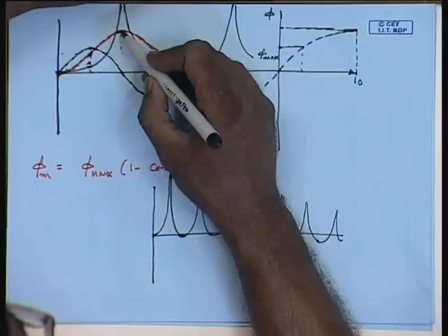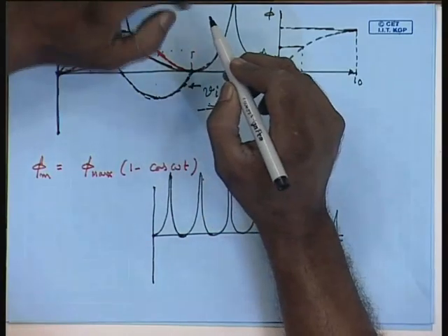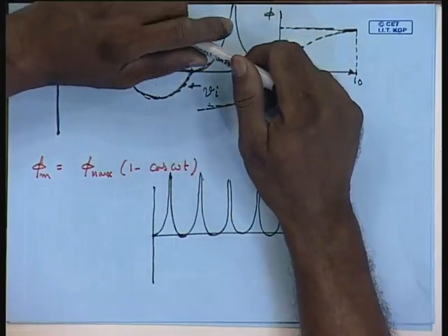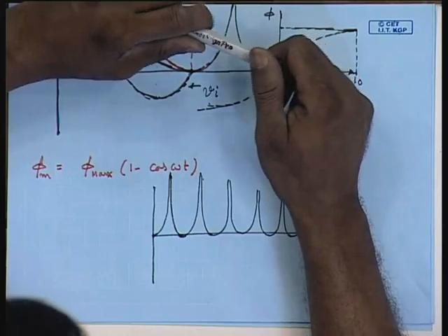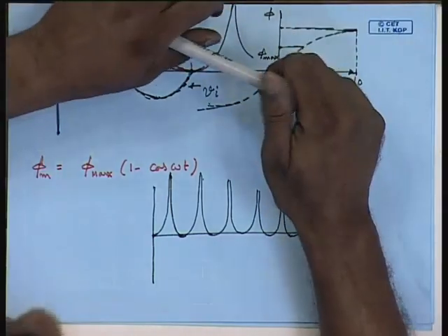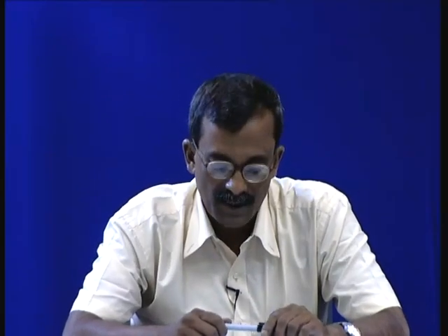This is called retentivity. So, if you have some remnant flux in the transformer, then the peak flux density may increase even more than twice the steady state peak flux, in which case the peak of the inrush current will also increase accordingly. On load though, this effect becomes somewhat less, because the flux decays fast and the peak value of the current reduces faster.